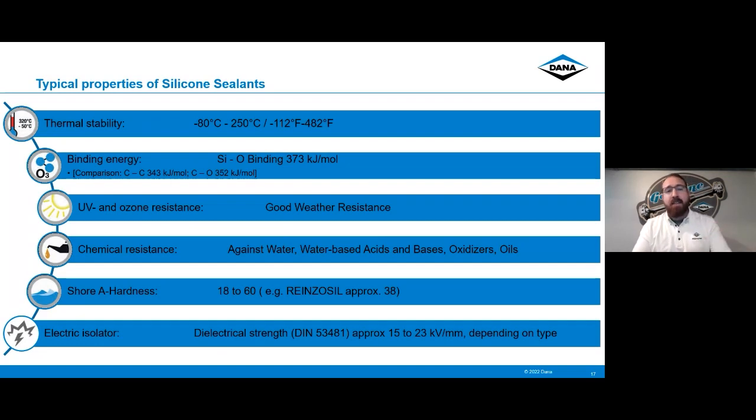So you need to make sure that it does have strong chemical resistance. It's not going to have severe swelling whenever it's touching a fuel or an oil, right? If you're doing a valve cover, guess what? There's going to be oil that's constantly up against the surface of that silicone. You want to make sure it's not going to break down.